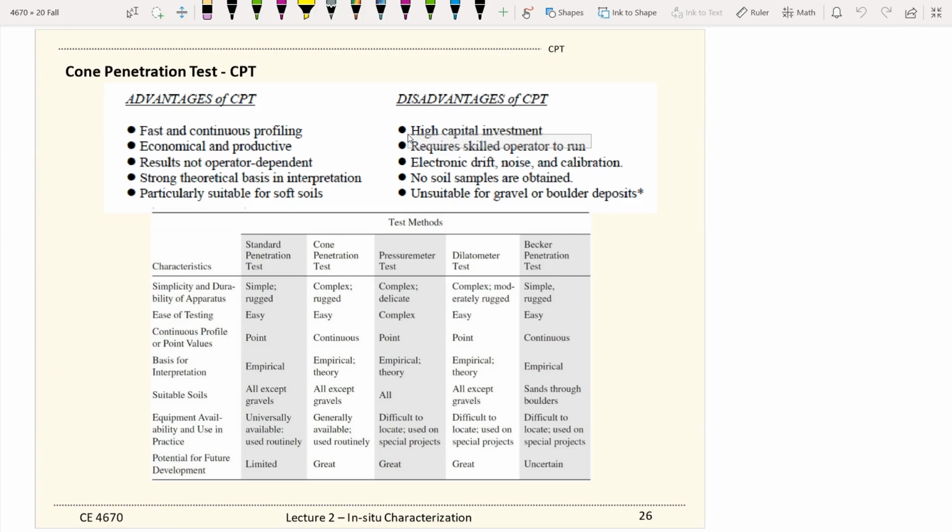I know some folks in geotechnical engineering who spend their whole career focusing on this, making themselves CPT experts. Since you have more electronics to deal with, the noise, the calibrations, and the drift from the electrical device matter. You need very good technicians to help you fix those issues.